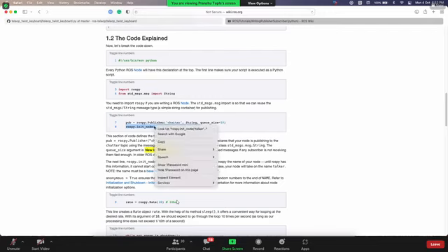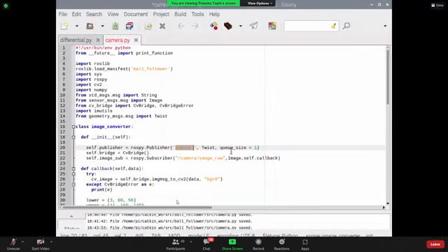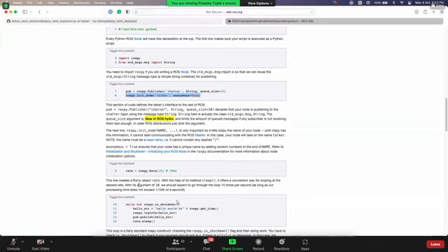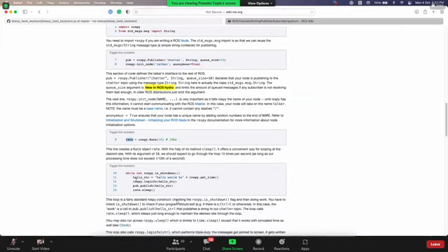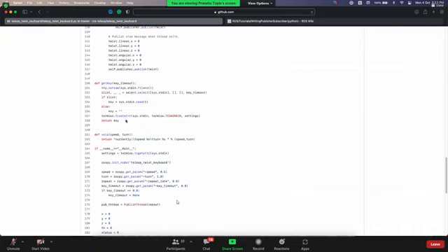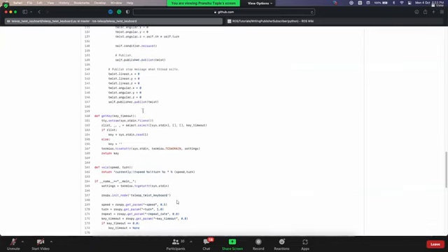Let's initialize the node. So I can put this thing, rospy.init_node. What do we say? Let's keep the name as Docker itself. It doesn't matter. And here, whenever we have to publish, what we say is pub.publish hello string. So here it is publishing a string message, but we want to publish a geometry twist message.